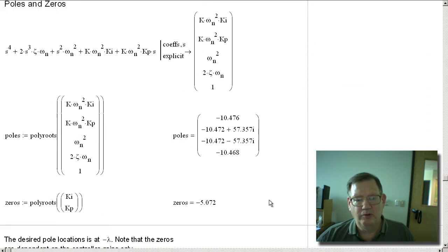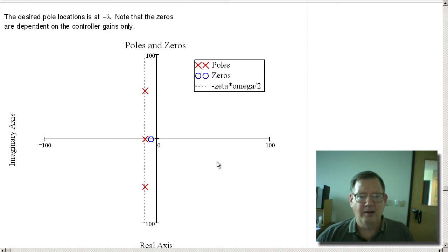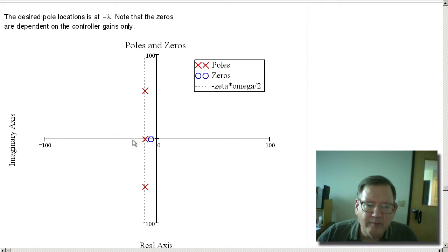And then I'm going to do the pole and zero plot. And this is where you have the best response. Now, like I said before, you can usually take the lambda part, the real poles, and you can move these back and forth. But if I move lambda this way, what ends up happening is the alpha term, the real part for the complex poles, goes this way.